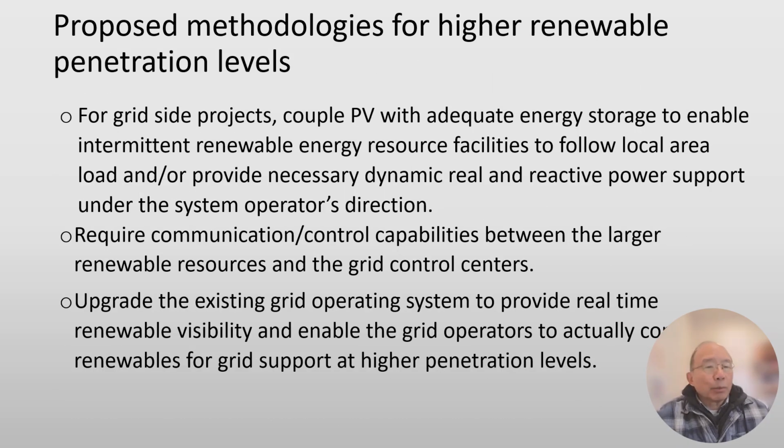For higher renewable penetration levels, for the grid side projects, couple these units with adequate energy storage to enable the intermittent renewable energy resource facility to follow local load and/or provide necessary dynamic real and reactive power support under the operator direction.